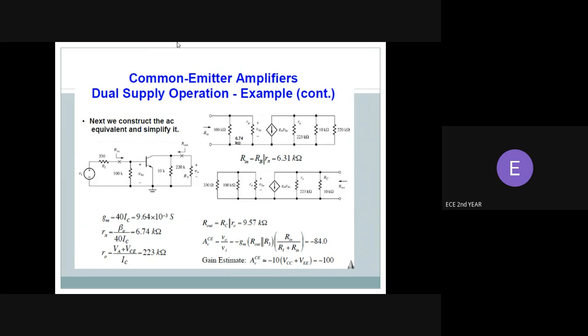Using this small signal analysis, I can analyze the various parameters in the transistor: the output resistance, the input resistance, the voltage gain, and including the current gain. The purpose of this circuit analysis is to simplify the analysis. Instead of dealing with the entire circuit, you can deal with only the AC operation, since the DC voltage is fixed and not going to change. With sufficient setup, I could analyze all the things in this circuit.